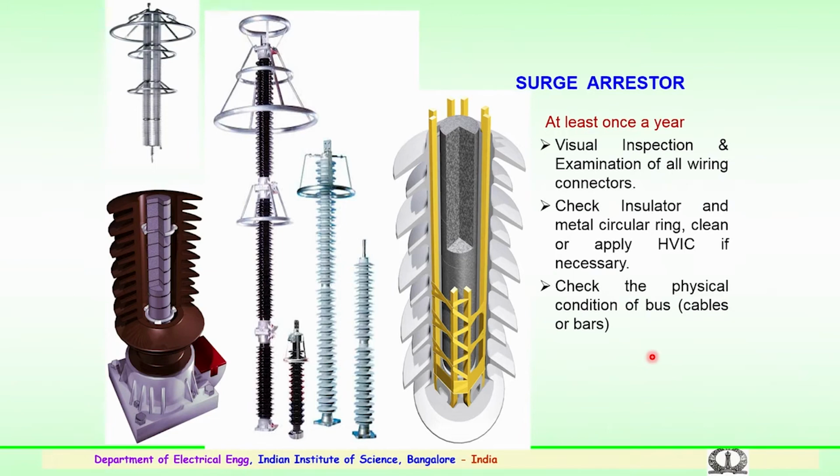So, this surge arrestor, as mentioned earlier, consists of various blocks of zinc oxide elements which are stacked inside, with a pressure relief, and the surge counting device near the ground side. You have a surge counter and also the leakage current monitor, which gives information about the performance of this lightning or surge arrestor.